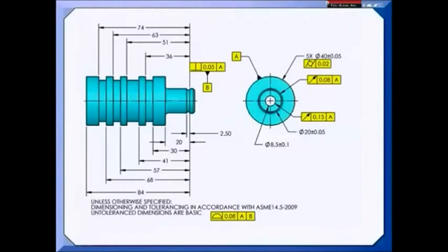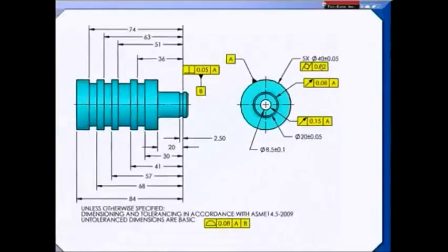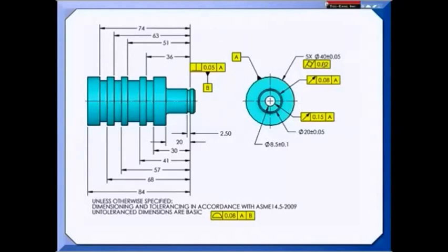Usually in assemblies we like to have interchangeability of parts, but that's not always the case. In some hydraulic and pneumatic applications where you want a metal-on-metal seal, the parts are selectively assembled. In other words, they're matched. Let's say that this is a spool for a spool valve in one of those applications. I would make up several spools and try to keep them very cylindrical while I allowed the size to vary. Notice that the size tolerance is bigger than the cylindricity tolerance by quite a bit. Then I would grade the spools, and then I would match them up to bores, and then I'd do a pressure test to make sure that they're not going to leak.